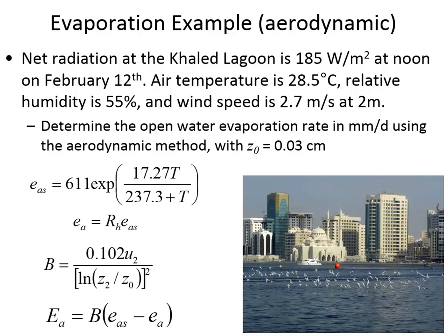Okay. Can there be evaporation at night? Is it possible for water to evaporate at night? Yeah, from the long wave radiation. It can evaporate, and it gets the energy from the ground emitting the energy. And so we know that evaporation has to have an energy source, and it has to have transport. So yes, there can be evaporation at night as long as there is something supplying the energy for the evaporation to occur.